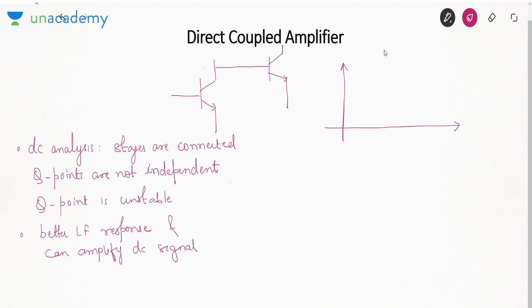So how does the frequency response look? We have improved the low frequency response but not the high frequency, because high frequency gain is low due to parasitic and stray capacitances. They are not removed. We have just removed the coupling capacitor.